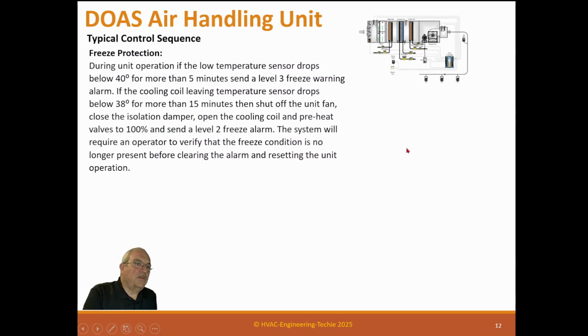Freeze protection. During unit operation, if the low temperature sensor drops below 40 degrees for more than 5 minutes, send a level 3 freezing alarm. If the cooling coil leaving temperature sensor drops below 38 degrees for more than 15 minutes, then shut off the fan, close the isolation damper, open the cooling coil and preheat valve to 100%, and send a level 2 freeze alarm. The system will require an operator to verify that the freeze condition is no longer present before clearing the alarm and resetting the unit.